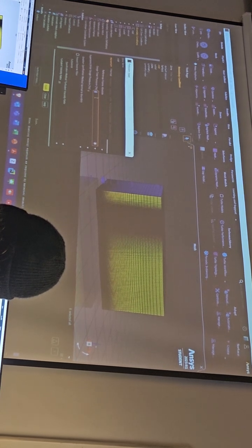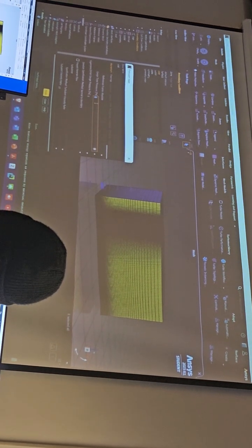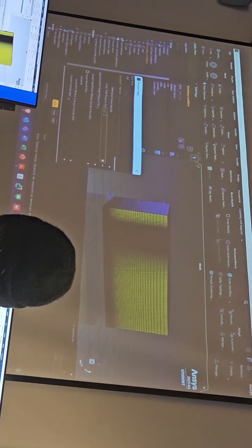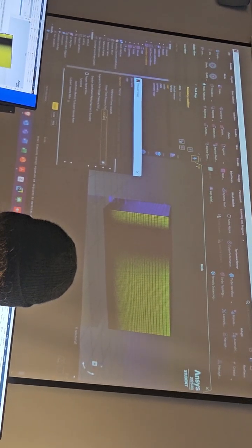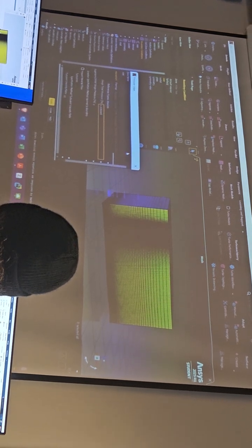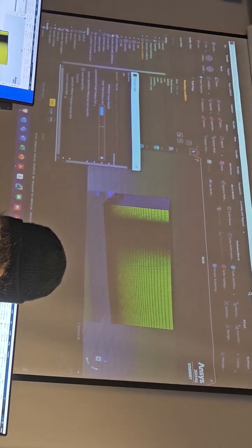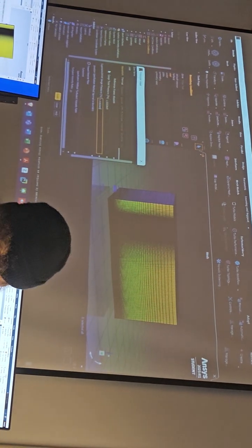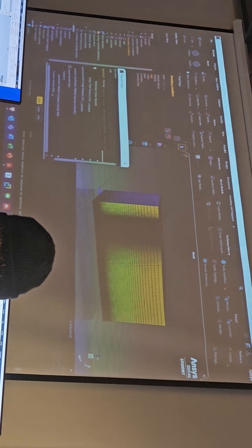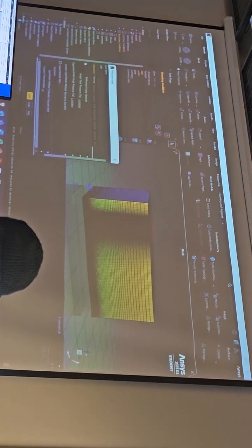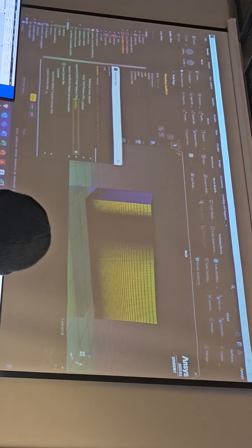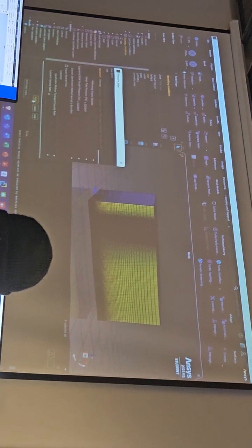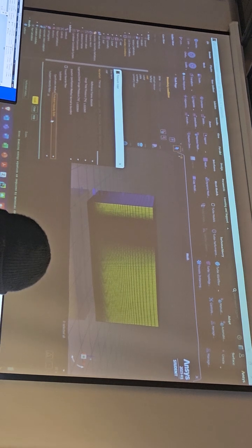And so we set as the gauge total pressure the value over there, that is 1.02828 e5 bar, so e5 means 10 to the power of 5. And I copy this value also for the initial gauge pressure. So when I'm initializing the solution, Fluent is using that value as the initial gauge pressure at the inlet. And I hit apply.